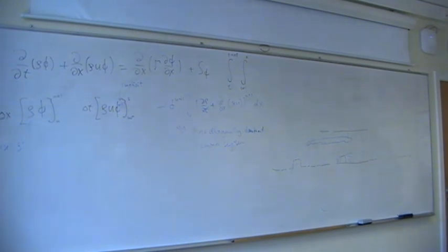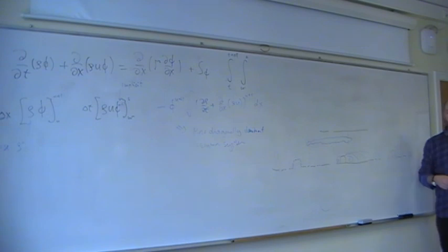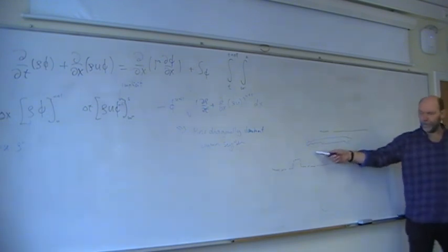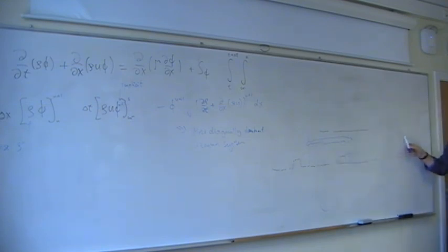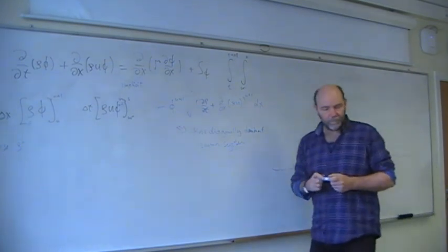But for you, it should be possible. Take two and then make periodic boundary conditions. It should be the same, and then see if you get any differences. You shouldn't. Of course, you have to double the amount of cells, but still possible. So that's an easy check for you. Do I have such long structures that are going to interfere with my boundary conditions? Okay, double the cells and take it all the way up here and see, does it change anything? No? Then you're good. Other questions?